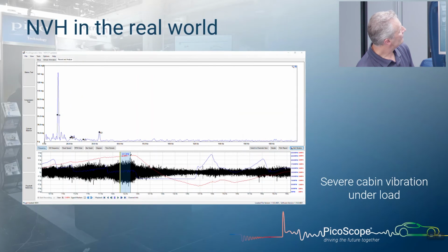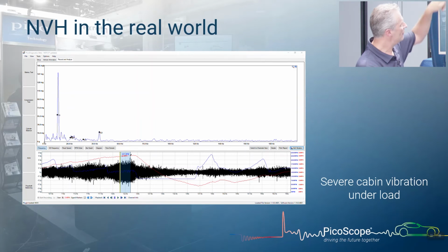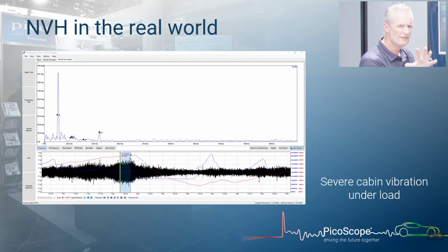Okay, so T1 in the real world. This one is incredibly powerful when it comes to looking at engine diagnosis. But be aware of something that can trip you up, and that is, at first glance, this peak here appears to be a T1 vibration. But in fact, if it is at 44 miles an hour when under load. If you're at 44 miles an hour when you're not under load, then this comes down. So it's kind of counterintuitive as to what it could be.